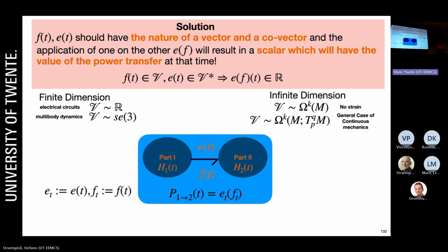So notation-wise, this is what Paynter at MIT introduced in bond graphs. He says, if I decompose the system and I want to talk about the interconnection between these 2 parts, there are always 2 variables involved. I need an object that represents these 2 objects at the same time, and he called that a bond. So this is a power bond, and you recognize it's different because it only has half an arrow. That's the notation that Paynter introduced in the 80s.